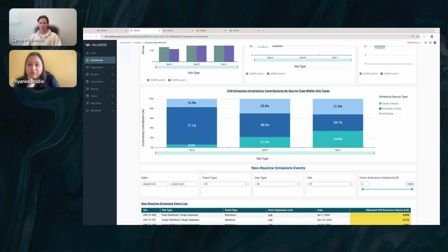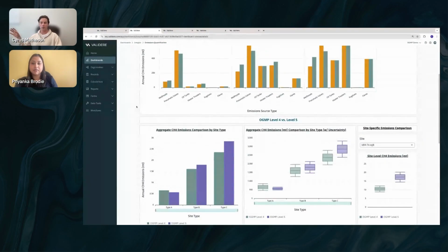Awesome. And one more from Tim: is the uncertainty at the source level assumed to be a normal distribution? For these specific uncertainty calculations, we were actually assuming a log normal distribution. We validated that. That's not an aspect of this that we really got into, but during an actual OGMP implementation, the calculations that we're encoding to perform those uncertainty calculations would all be accounting for the shape of those distributions.